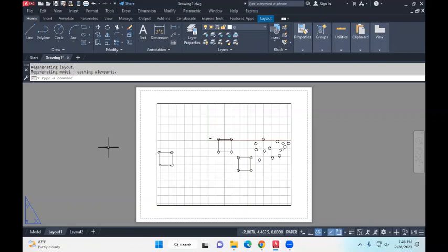Yes. So the obvious difference would be the scale, which is 1:1. It will be of the original same size, right? But the one which you printed out on a scale of 1:2, it will be smaller than the one which you drew, okay? Because it is a reduction scale, 1:2, right? In other words, 1:2 is 1 divided by 2, which is 0.5, okay? So reduction by half, okay? Got it? So that's the difference between scales.